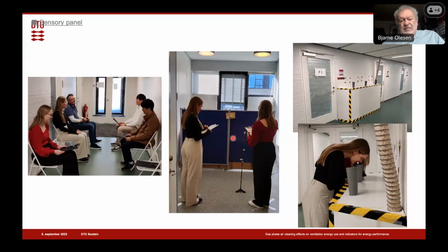And there are two ways we do the testing. Other people go into the space quickly, and in the first take two deep breaths, and then they evaluate the level of odor, the perceived air quality they feel. Or, which we have done here, on the right-hand side, we take air out of the space, so people don't go into the space, but they have a funnel where the air from the space is being provided.